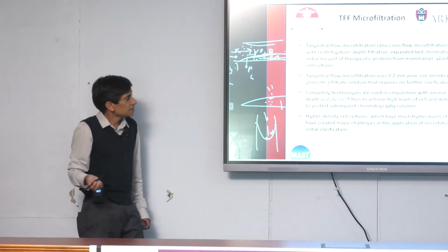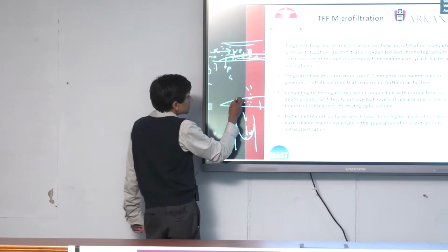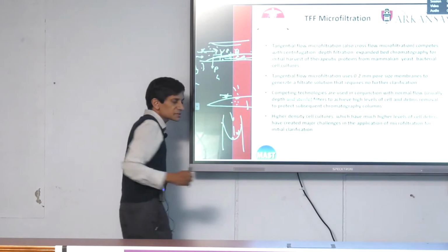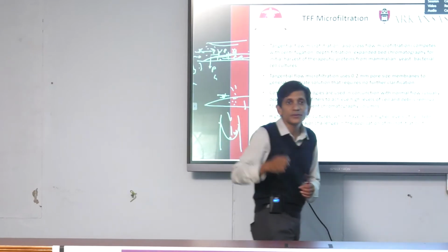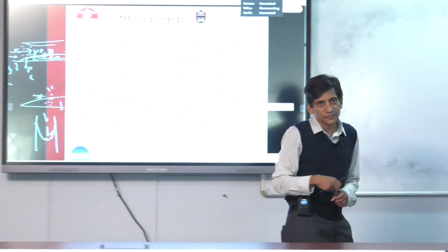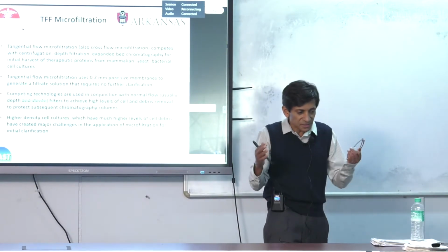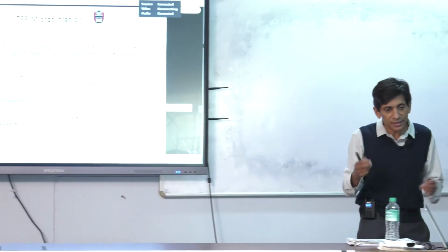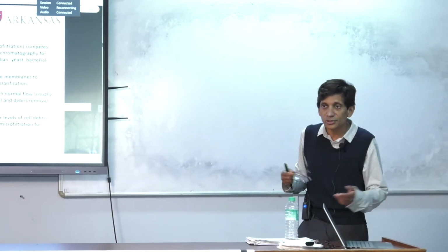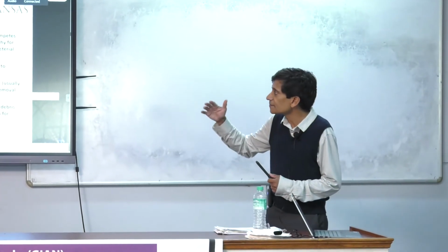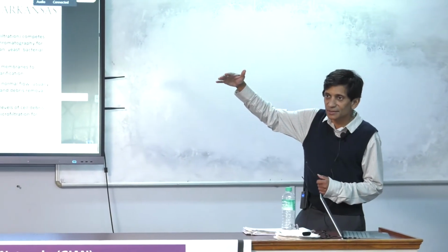That's one thing. There's another thing that can happen, and that is if you have a particle here, we talked about the shear stress acting. So there's a shear stress acting to pull it along, and here there's a lower shear stress that will also tend to cause it to expand and move away. So that's called shear-induced diffusion. So basically, there are these various mechanisms, and these are not just made up. These are real ones that you can actually go and you can study, okay? And then they are shown in fluid mechanics. So the point is, for microfiltration, when there's particulate matter, there are many back migration mechanisms, okay?